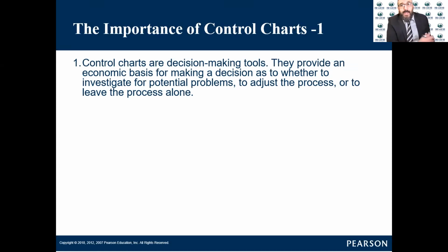It is a decision making tool that will help us investigate, go deeper, and see what the cause of the problem is. This tool will help you make a decision on adjusting the process. Do we need to adjust it? Or maybe not. After studying the control charts, there's no need to change anything, so just leave the process as is.